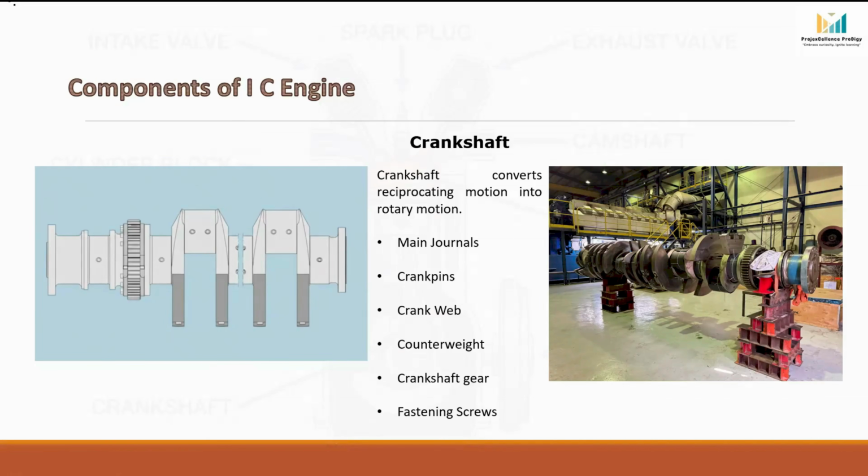After lubricating the big end bearing, the oil further travels through passages inside the connecting rod and reaches the small end bush and gudgeon pin area. From there, through the piston skirt, oil reaches the piston rings for lubrication and the underside of the piston crown, where it absorbs heat and helps keep piston temperature under control.